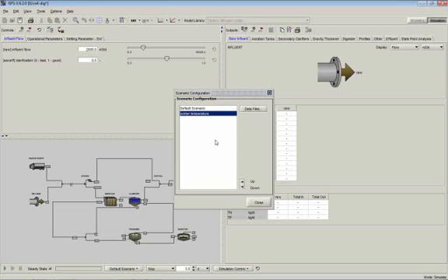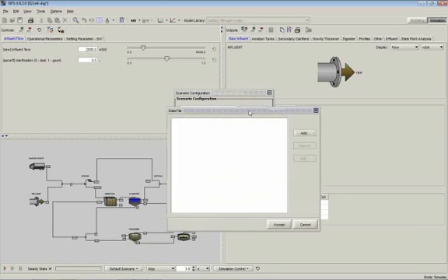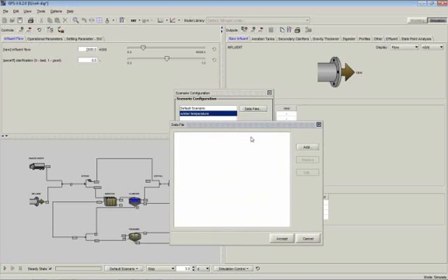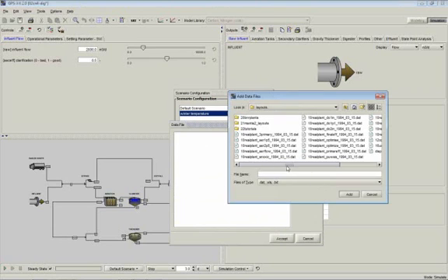Another feature that is extremely handy, and I've been using quite a lot now in my past couple of projects, is the ability to set data files specifically for a particular scenario. So you pop up that data file button there and you can hit add, and then it brings up a browser where you can browse to your data file that you have already prepared. Now within that data file we still use that GPSX structure of putting the names of the variables at the top, and then you have your time series of data below. But now you can just browse to that.